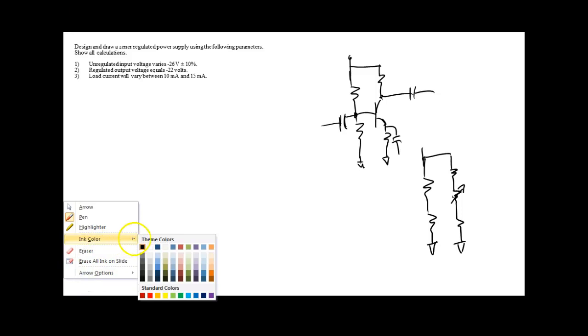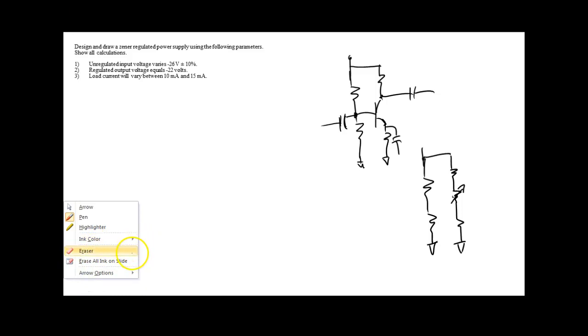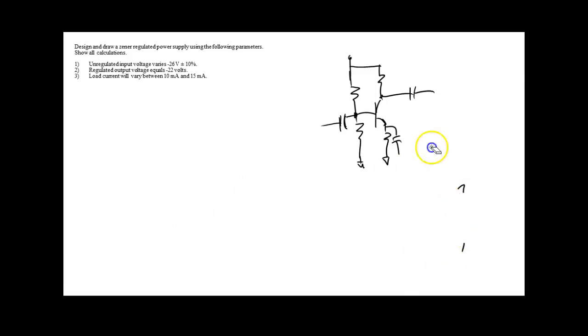You're going to find out that most of the formulas that we learn in these solid state devices are formulas that you learned back in DC, but these are active devices. A Zener literally dynamically changes its internal resistance to maintain a constant output. If the current flow goes up in it, it keeps the same voltage drop. If it goes down, it keeps the same voltage drop. It is not a resistor. It is a solid state device.